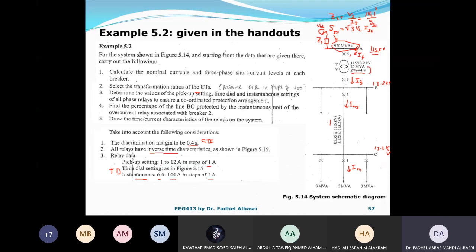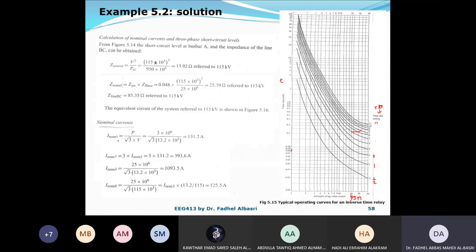So I will get it from this rating and the low voltage side. And this is I nominal 4, which is obtained from the rated power and the rated voltage at the HV side. So this is straightforward. I nominal 1 is the power of the load, S load. Normally we take S over √3 V line.